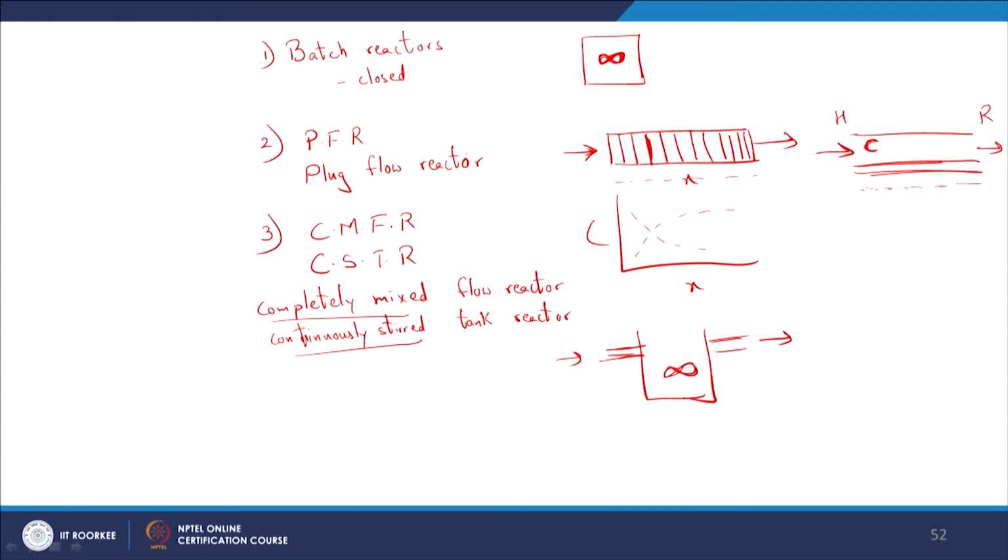So again, you have complete mixing continuously. That is the scenario you need to conjure up whenever someone refers to a CSTR, or completely mixed flow reactor. What can we approximate by using this reactor? Let us say a lake, but obviously there are a lot more assumptions involved here, especially with respect to mixing.